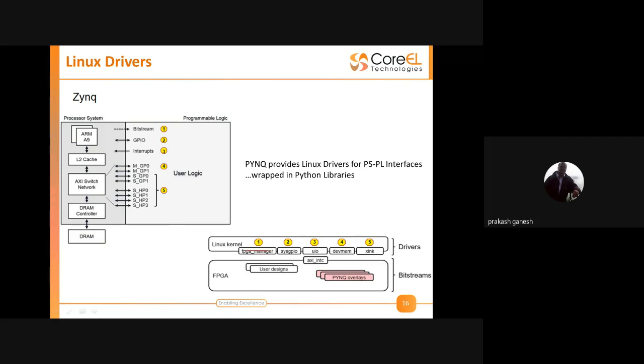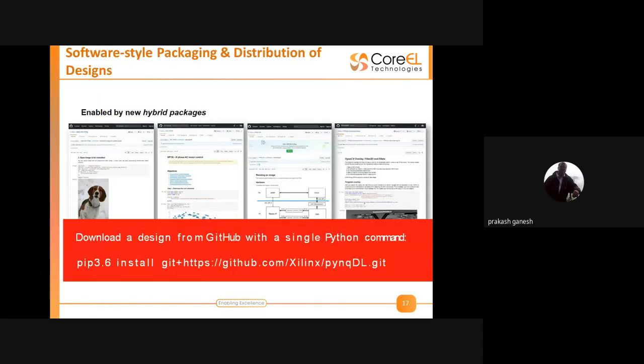If I'm having any peripheral with GPIOs, I have a system with GPIO drivers. If I'm having an interrupt, I'll be having what we call UIO drivers. If I'm having some memory mapped IOs, I'll be using device memories. And some Xilinx specialized device drivers are there, you can use those also. Am I clear? Any doubts to me till now?